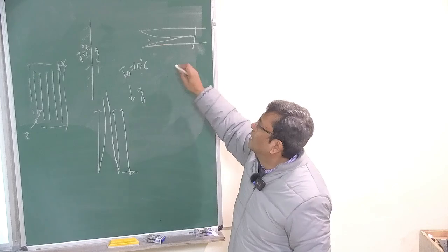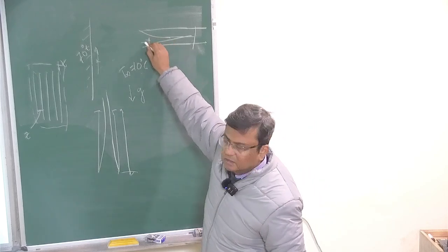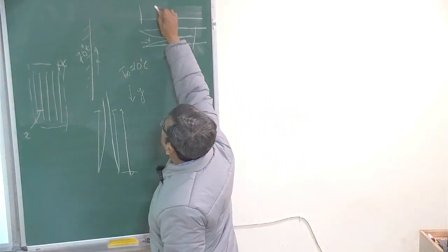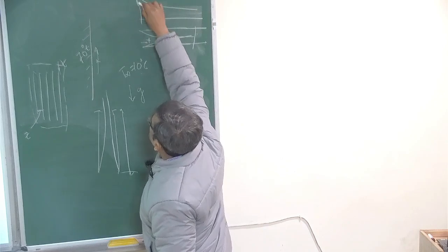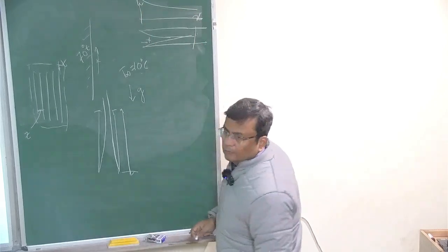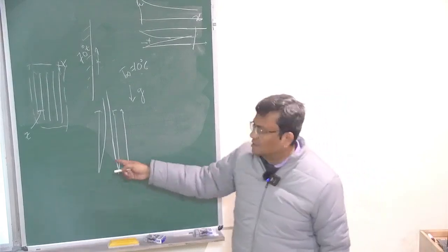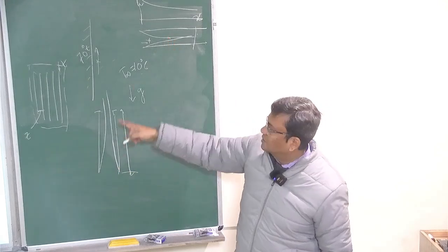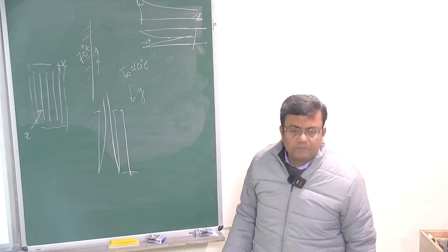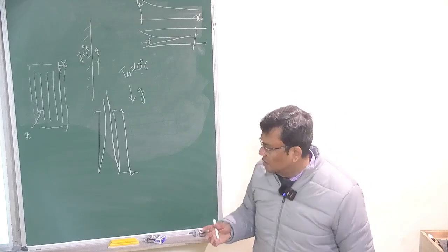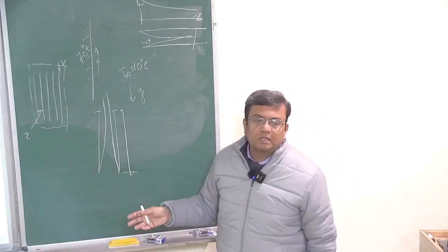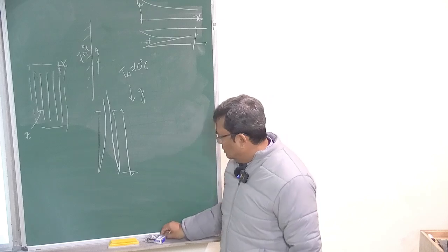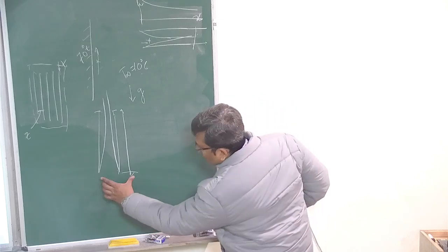Okay. So heat transfer coefficient is higher in this region. Then the heat transfer coefficient will taper off. So if you have flow in a duct, forced convection, heat transfer coefficient should go like this. Something similar happens in these channels also, even though this is natural convection. This is forced convection, this is natural convection. Not exactly the same thing, but the boundary layers are thinner here, so that will give you higher heat transfer coefficient.